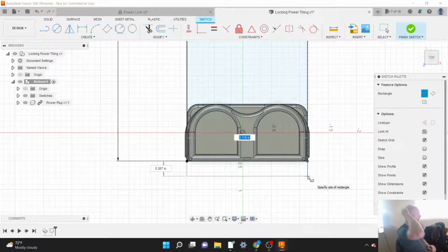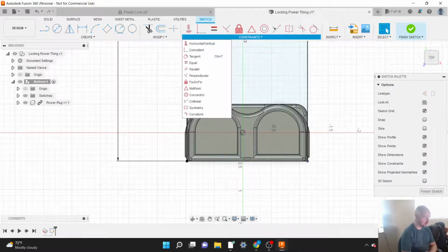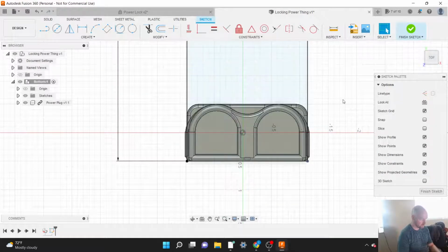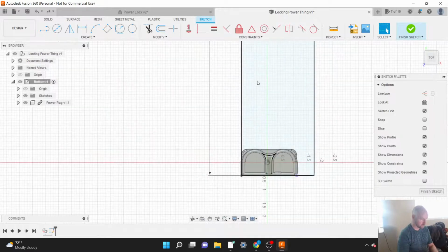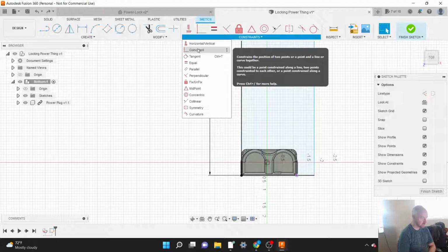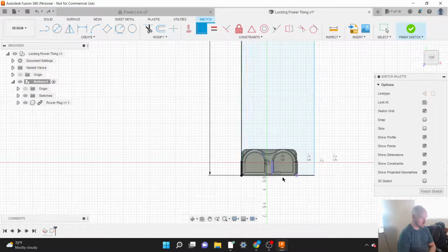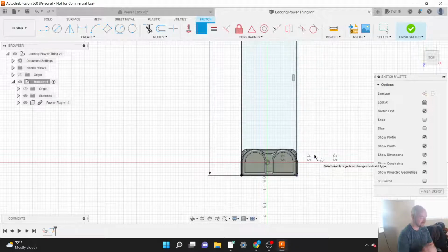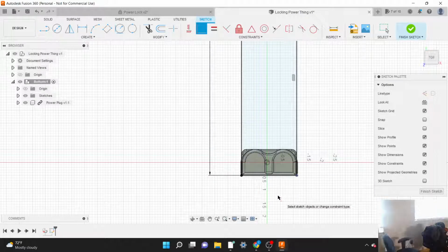Which constraint again? I chose to use the coincident constraint. Okay. And here, if I just Command Z, so if I come up to constraints and then choose coincident. And you clicked on the dot first or the line first? I clicked on the dot first. Okay. And then I clicked on the line second. Okay, and it tells me failed to solve. Let's see why. Ah, you have a dimension there.